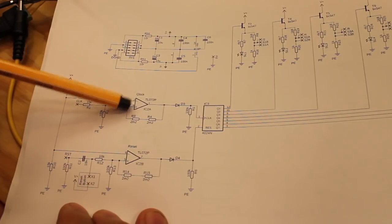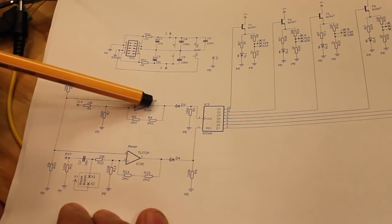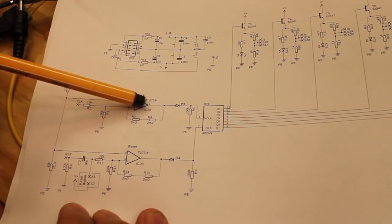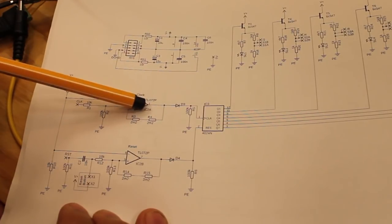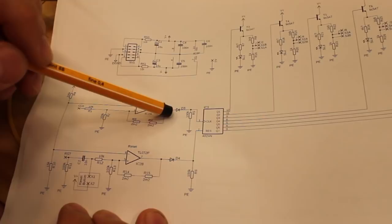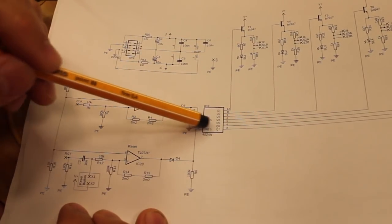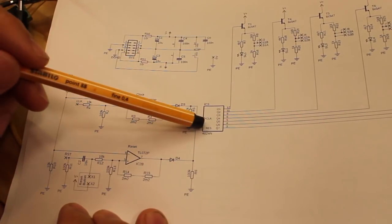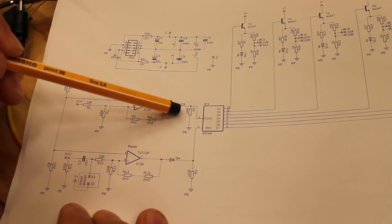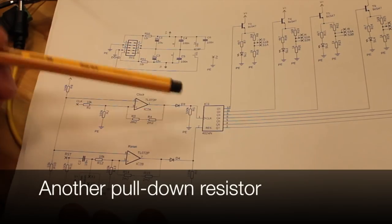So it just goes up to 2 volts, and as soon as it goes over, the comparator circuitry changes it from minus 12 volts to plus 12 volts. And then we have a diode afterwards, because we don't want the negative voltage into the 4024 or an Arduino or anything like that. There is also a 100k resistor to ground after the diode.